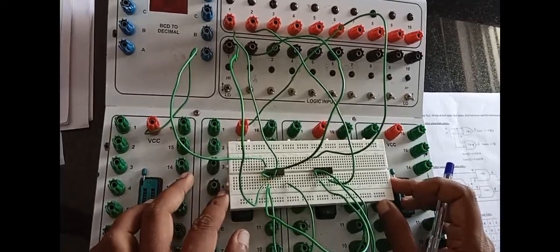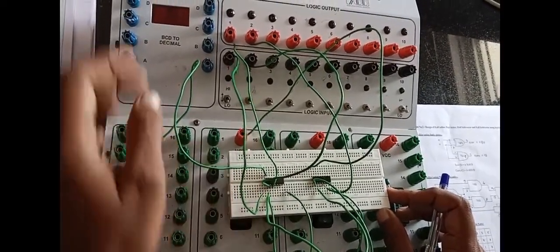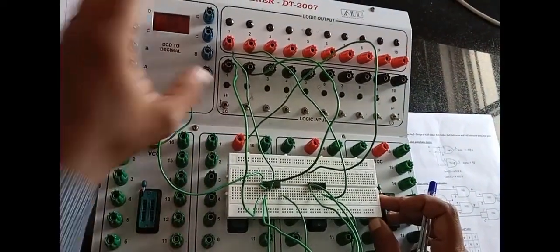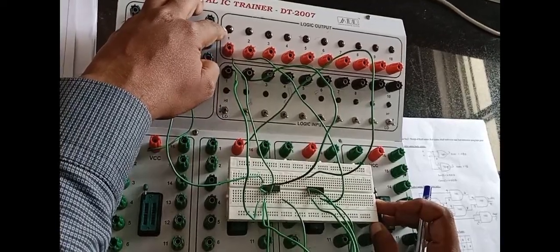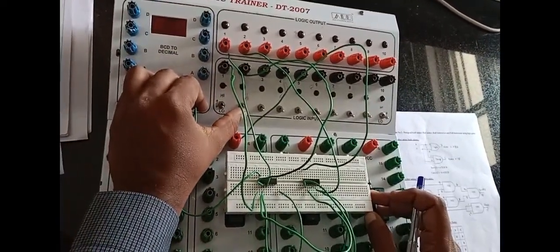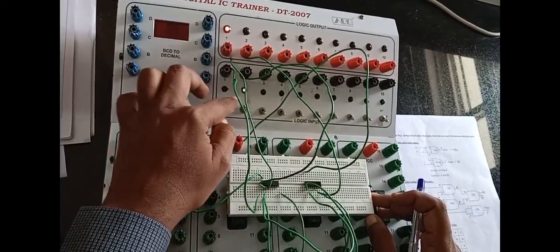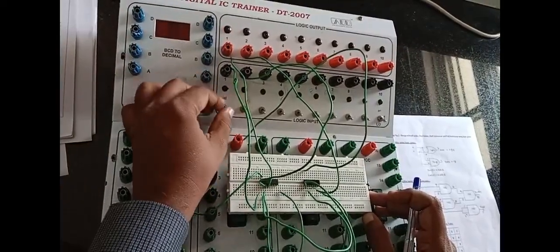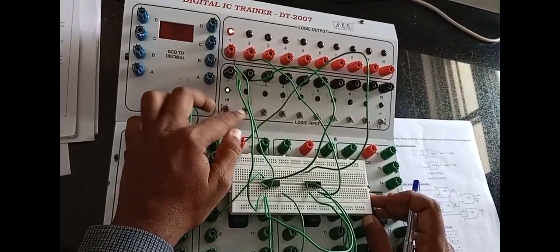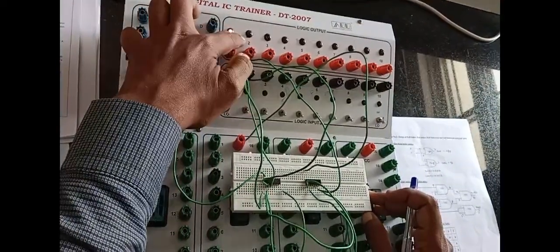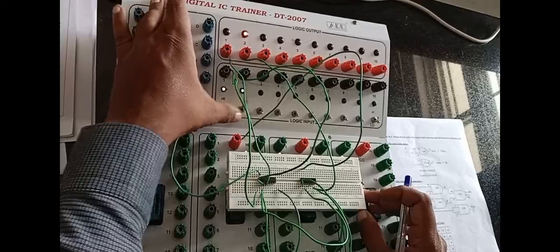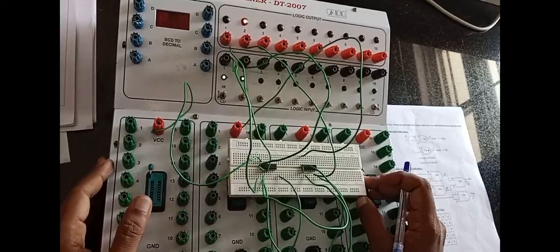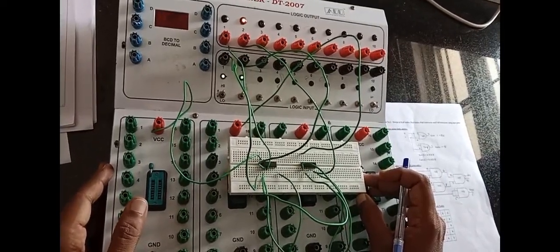Next, I am going to verify the truth table using the inputs. Here both inputs are at 0 value, that is low value, on 1 and 2, that is A B equal to 0 0, means output also 0, from the truth table. Next, I am going to modify the input: A is 0, B equal to 1. In this case, input 0, 1 means sum equal to 1, carry equal to 0. Next is 1, 0. Input is A 1, B equal to 0. Sum is 1, carry equal to 0. Next, both inputs are high, that is value 1, means sum will be 0, carry is 1. From this implementation, I verified the truth table using basic logic gates.